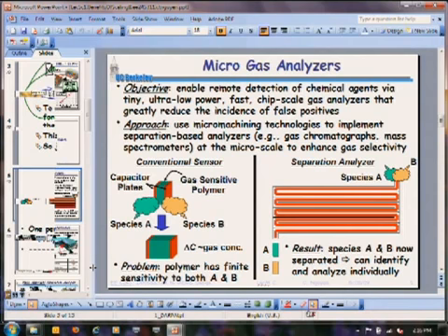Because you think of it, everything is a sensor, right? Say I wanted to sense temperature. Everything senses temperature, right? Even a quartz crystal will sense temperature. Its frequency will shift with temperature. Any analog circuit will sense temperature, right? The currents and the voltages will shift with temperature.